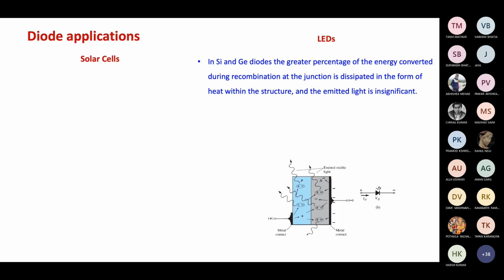So in LED, in summary, what we can say is, as soon as we apply a positive voltage, it reduces the barrier in the LED, and that results in a lot of carrier diffusion across the junction, and that also results in recombination of electrons and holes, and that gives us light. Okay, that is the very basic function of the LED. Any question here?